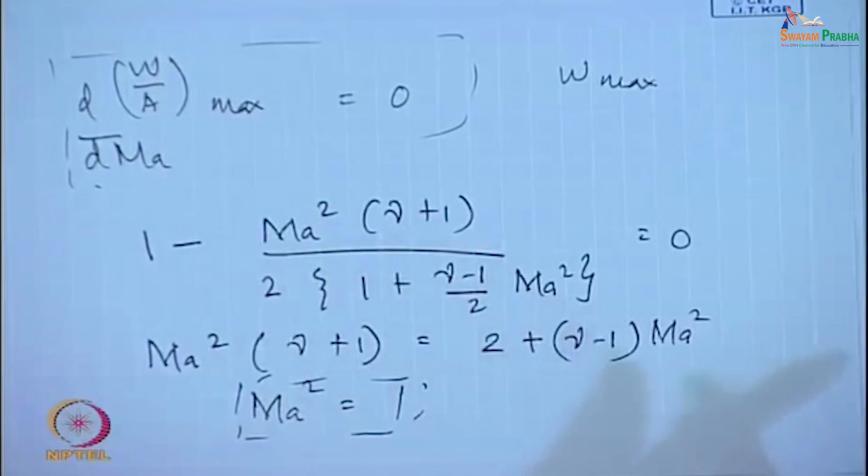So, therefore, we were talking about the choked flow conditions, or rather we were talking about dA equals to 0, when dA equals to 0, M A equals to 1 and so on and so forth. And we find why M A equal to 1 is so very important, because that gives us the maximum flow rate from the converging nozzle under the present circumstances. Okay. So, therefore, we find that for Mach number equal to 1, we get the maximum flow rate under the present circumstances. The discharge is maximum.